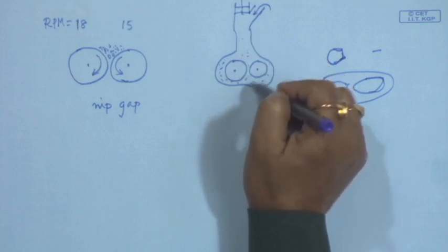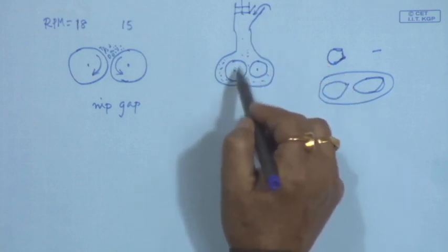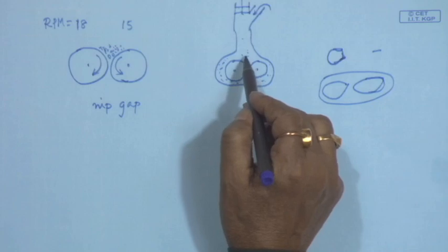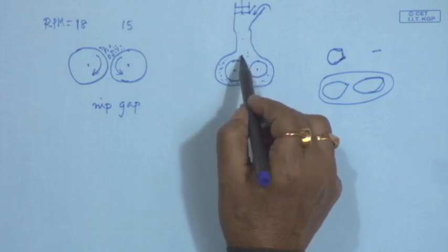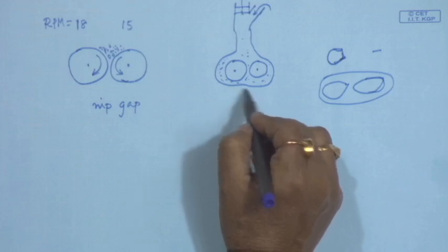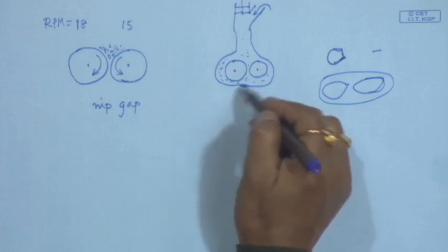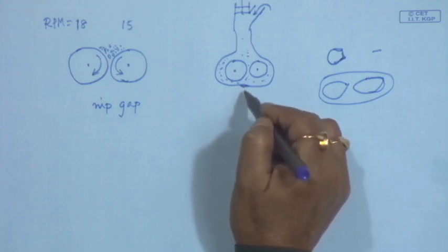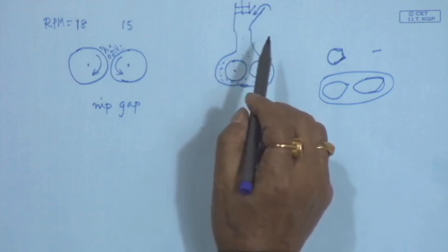So, this way we get a facility of polymer mixing in a closed chamber, and there can be a dumping door at the bottom. After mixing, the mixed product can be dumped down from here. So, that is known as an internal mixer.